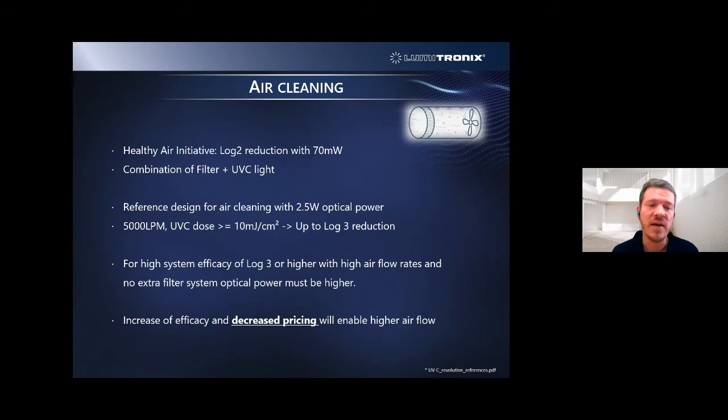But this system is just doing a log3 reduction at 5 liters per minute, which for an air cleaning system is not as much as you'd like to have for larger rooms. So for a high system efficacy of log3 or higher with a high airflow rate and no extra filter systems, the optical power must be significantly higher. So we're talking about optical powers of 10 watts or more, which are demanded for such systems.